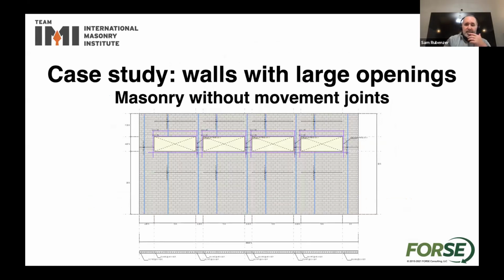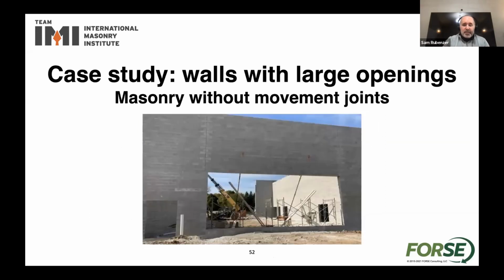This is another example. This is just one wall of a gymnasium. This is repetitive big openings. Again, people like light coming into their buildings. They don't like to live like engineers in basements. The light is good for people. And so we have these big openings that get added to structures and schools and gymnasiums. Maybe the rest of the gym all has the typical common 25-foot strategy used, and then you have this one wall. Maybe we don't have any control joints. We just take all of that reinforcement, make it continuous, and that works very nicely for this design.